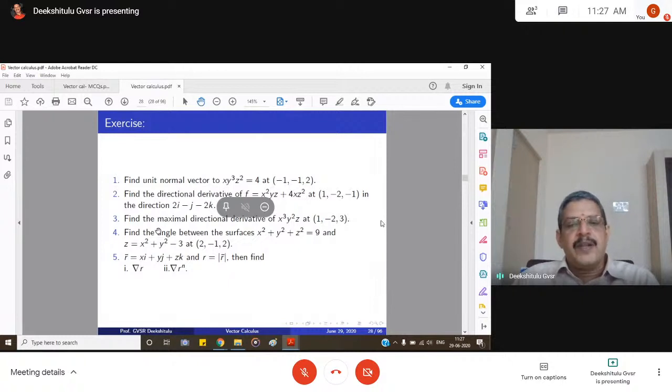The equation of continuity for incompressibility is del dot v equal to 0. That is a very important application of divergence in fluid mechanics. If f bar represents the velocity function in 3 dimensions and the fluid is incompressible, then the equation of continuity is del dot f equal to 0. Divergence of the velocity point function is 0. That gives you the equation of continuity.